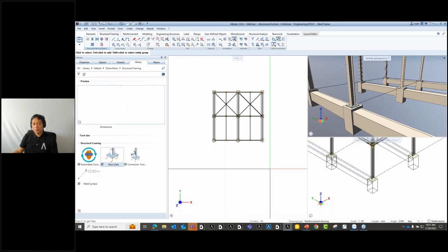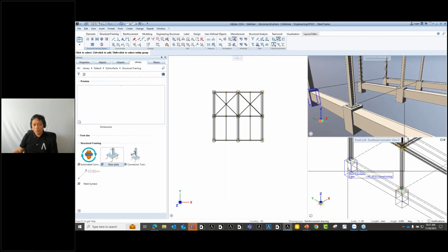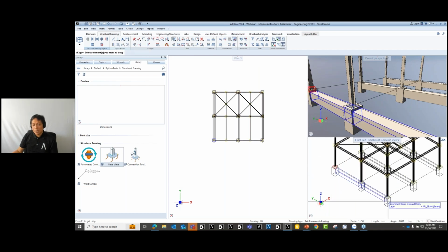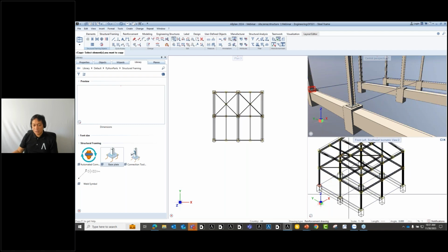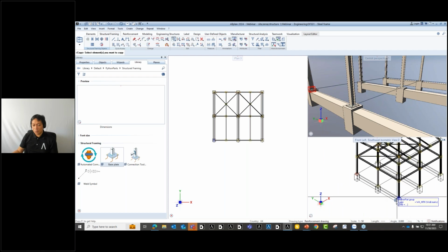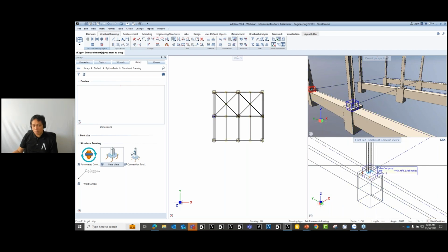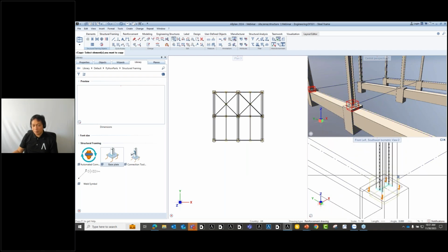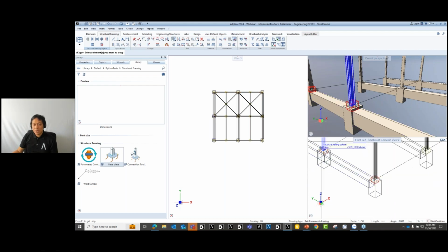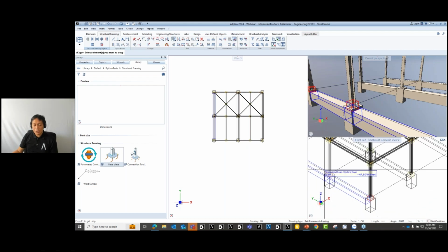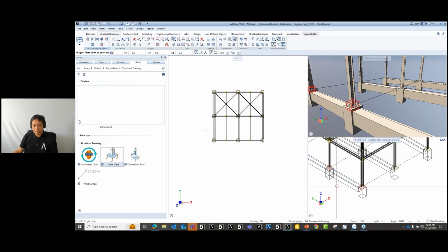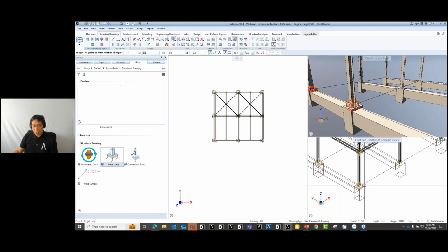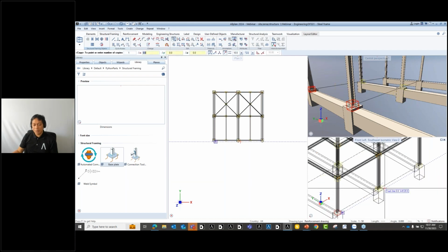Okay, so of course, since they are Python parts, you can also copy them. Copy from this, since this one is the same as this one, and then these two are the same all throughout. So I can say just copy all, because of course the offset considers the overall dimension of the column. So you cannot just copy one and then copy to all. Of course you need to copy those similar parts or similar elements. So from here I can say this one.